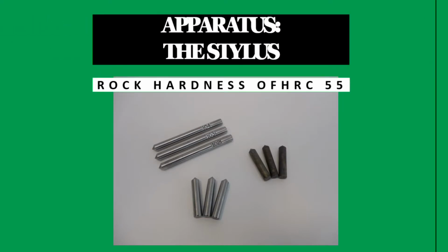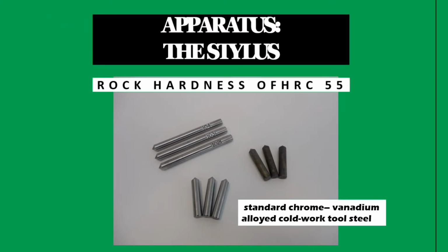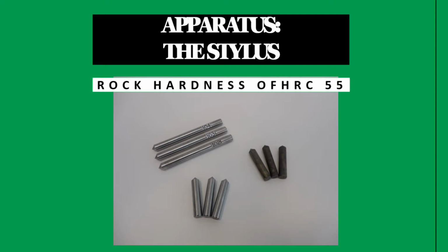Now let's go to the stylus. The stylus should be manufactured of a standard chrome vanadium alloyed cold work tool steel, which should be tempered to the desired hardness. It is strongly recommended to employ only a stylus tempered to Rockwell hardness of 55.